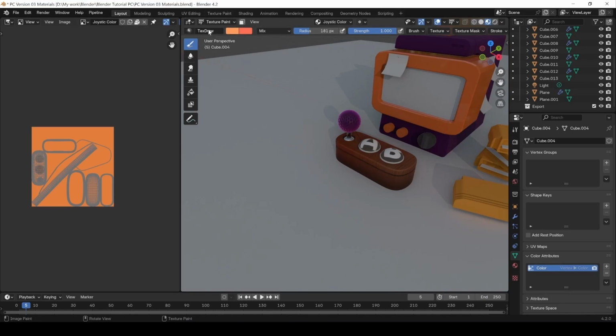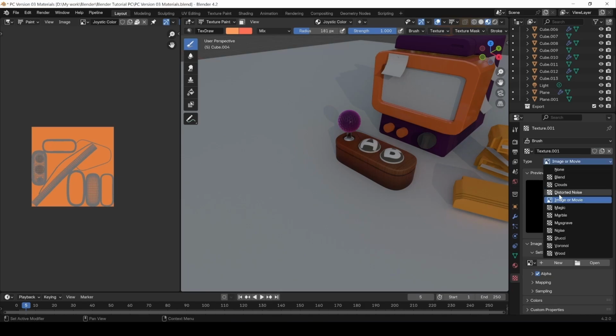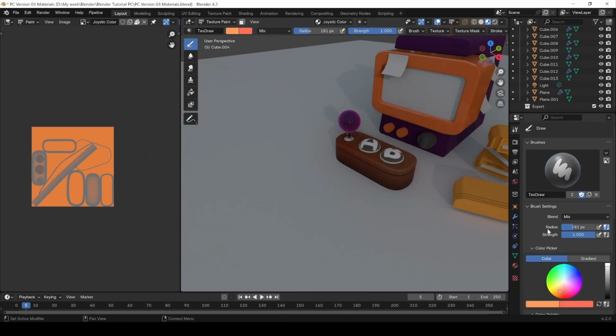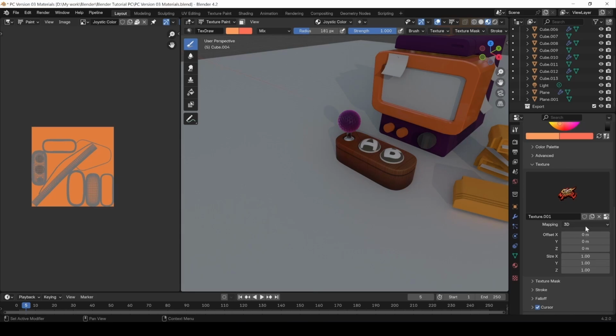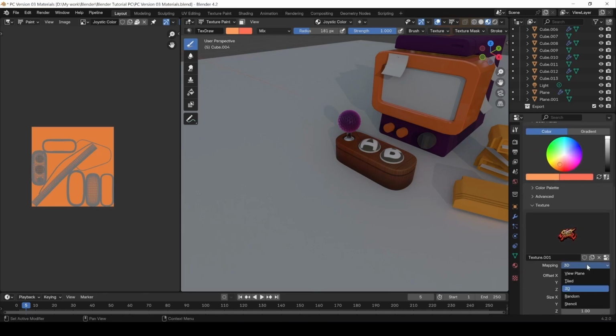Well, you go to texture painting. When you are in texture paint, don't forget to change this to paint, because if it's not in paint you can't really color. And what you will do is you will have a stencil here. So let's go to here, create a new one, and here it says image, we choose from here, but we can actually go and choose something right here, logo resize it, and I choose it. When you do this, you can go back to your color here, then in your texture, with this texture, you can choose stencil. And when you do that, you have it right here.